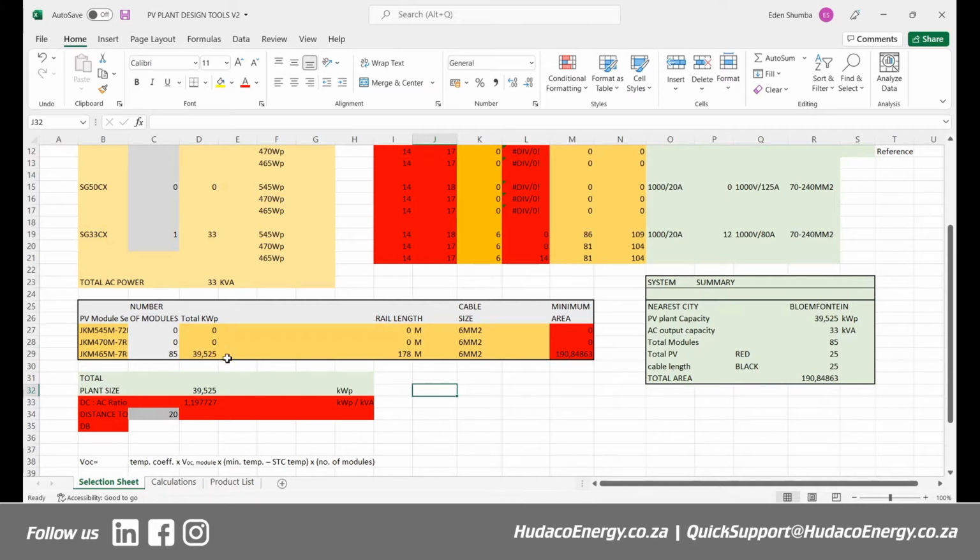This is now 39.5. So there's only a slight difference because of the 5 watts peak difference between the two panels, right? But with these ones, you can easily play around with the DC to AC ratio until you are at a nominal value that you think is ideal. For example, if we now put it at 90 panels, we're around 1.25, which we recommend most of the time.